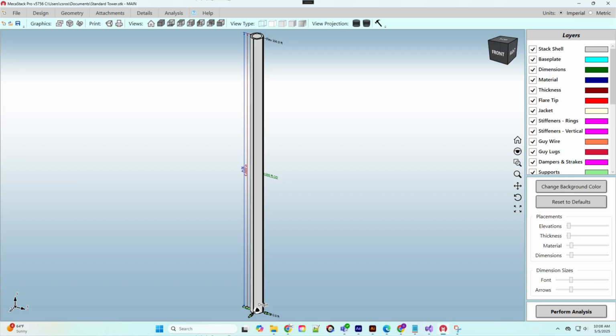It is important to know that stiffeners added to the vertical stiffener screen here are only going to be considered in the combined section properties of the cylinder with stiffeners. No check of the stiffener itself will be performed. If a vertical stiffener is specified in the breech entry, then if one of the Troitsky methods is used, the stiffener is going to undergo different checks to ensure that it meets those requirements.